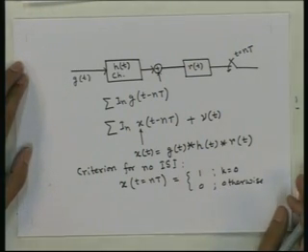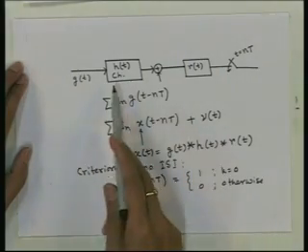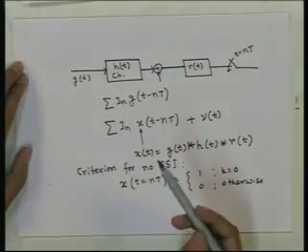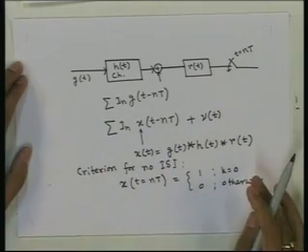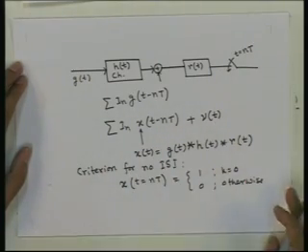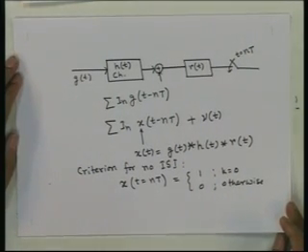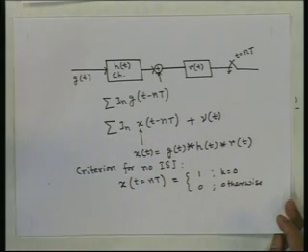So, often what is done is, if the channel is changing with time, you may not consider the channel, you simply consider r(t) and design g(t) accordingly and work with some suboptimal system. It may not be exactly ISI free. Then we would try to remove the ISI in other manners, which we will discuss in this class.